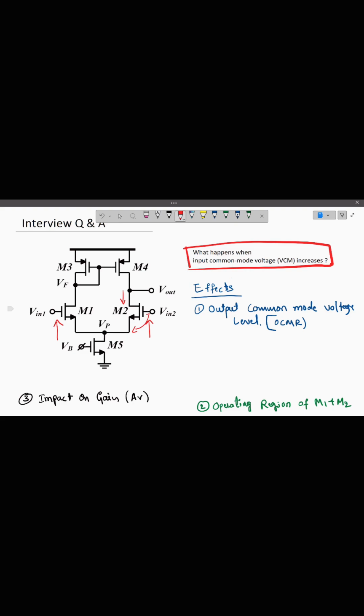because the VGS of this particular MOSFET and the VDS of this particular MOSFET try to increase. Though the VGS of M2 or M1 is slightly increased because of the tail current source M5, there is a slight decrement in the Vout. So now the Vout minimum, whatever we have existing, will start dropping by some amount. If the Vout of M1 and M2 starts dropping down, that essentially creates the issue of the VDS requirement. Now the VDS of M1 and M2 will start getting decreased.